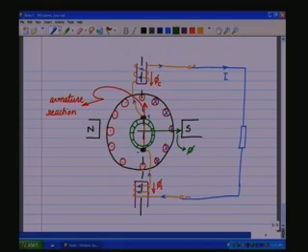See that the phi C flux opposes the armature reaction flux. So, if the number of turns on these poles are so matched such that phi C cancels out the armature reaction flux, then the only flux that would exist is the north south pole flux, and the orthogonal plane would still be the neutral zone.